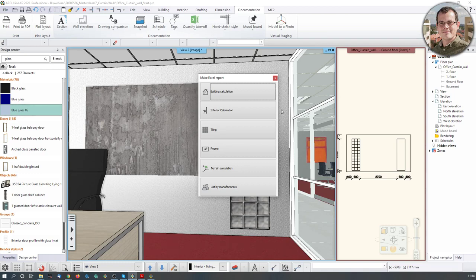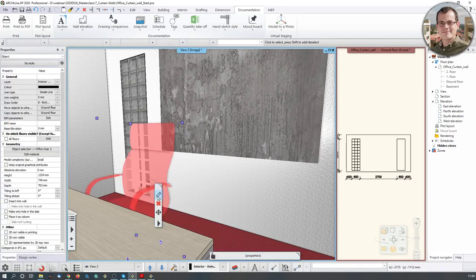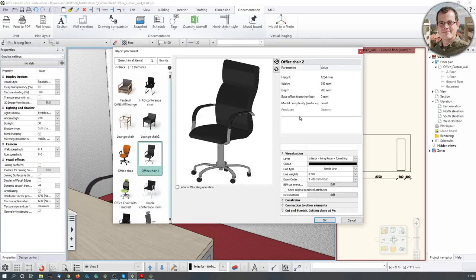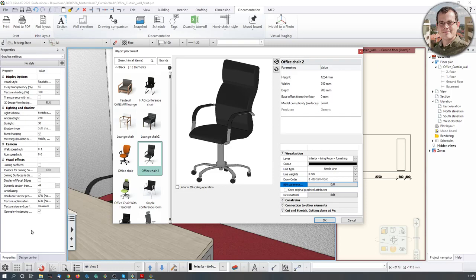But if you're looking for quantity takeoff, schedules, and this kind of thing, then this is where you can find them. There's another question. Is there a way to create the 3D parts first and then attach the part information one by one for documentation extraction? Again, this really doesn't concern today's topic, but here you can do that. If you're talking about adding data to a 3D element, let's just assume that this is the element in question. You go to pencil and you just add the elements over here, so you can add beam parameters to any kind of element, for example to this chair. If you know the manufacturer, then you can fill up this data, and then that data would be part of your export.